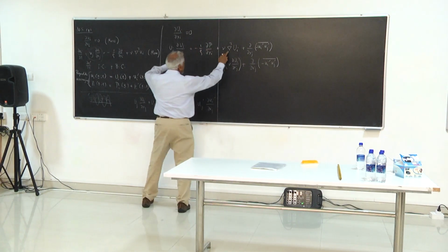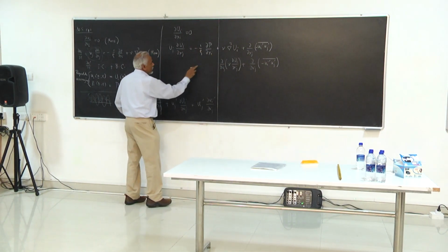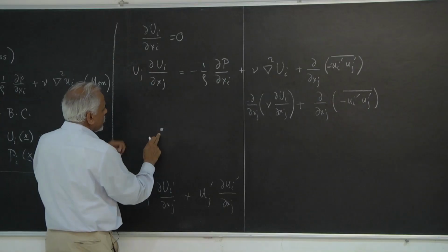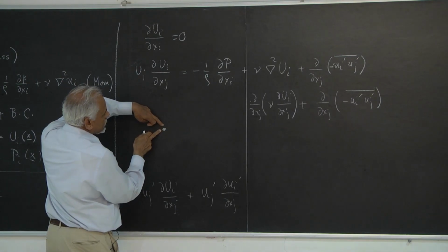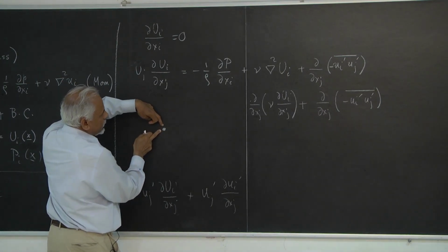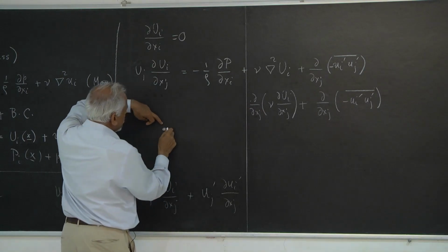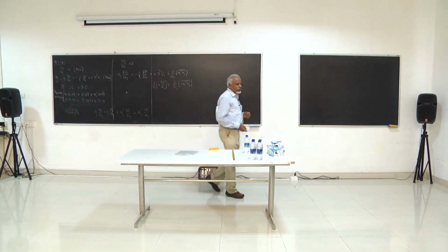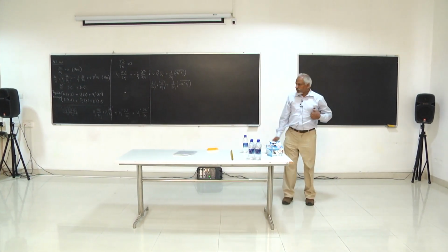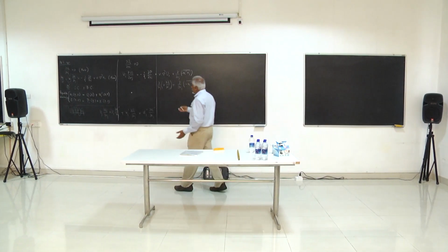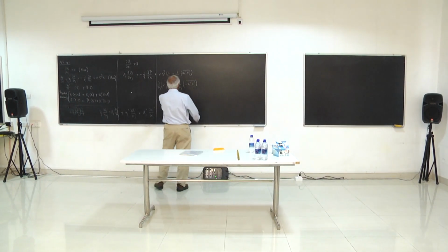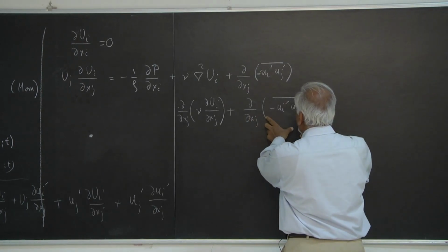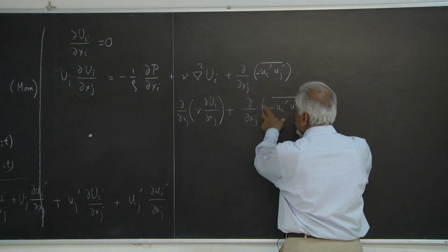So if you think about this, what is happening is, what is this term here? So I have, let's say, a fluid parcel, and the momentum of the fluid parcel is lost by viscosity if you have a gradient in the flow. So it's the fluid parcel, you might imagine, rubs against neighboring fluid particles and loses momentum by friction, or gains momentum in some cases, for instance. Here, you have a very similar thing that is happening, and the momentum is lost or gained by fluctuations.